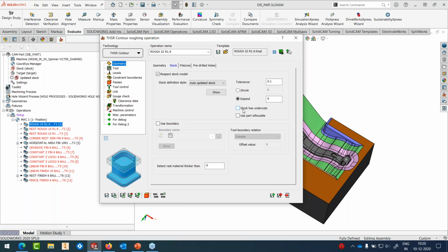So you have got a stock that really cannot be machined. But in many softwares, even if you provide a stock with an undercut, it doesn't recognize the undercut and just generates straight tool paths there. It's useless. It's cutting air because there's really no stock. When 3-axis softwares look from a particular direction and don't see anything but straight walls, they just see a straight wall. So they go and machine completely.